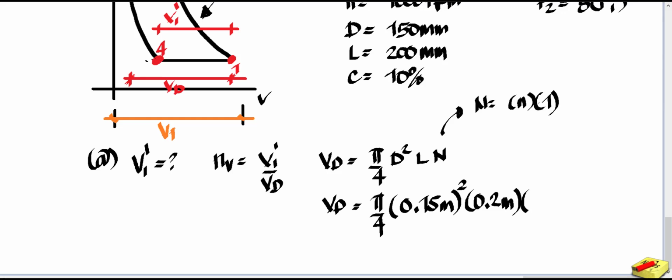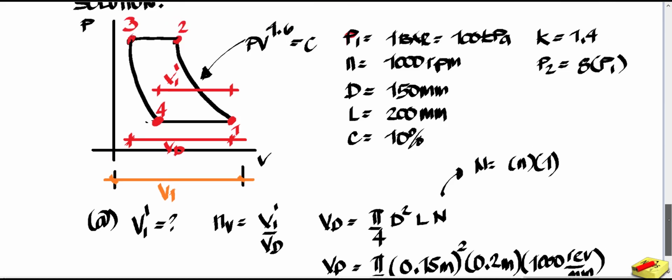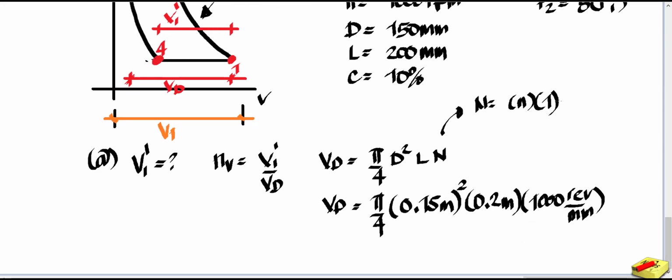Now, since the problem states that it is a twin cylinder, we have two piston in a cylinder arrangements, 2 sets. But it is a single acting compressor. So I'm going to put here the RPM. We have the given RPM of the system of the electric motor, that will be 1000 revolution per minute. Then for single acting, we're going to put it as 1.